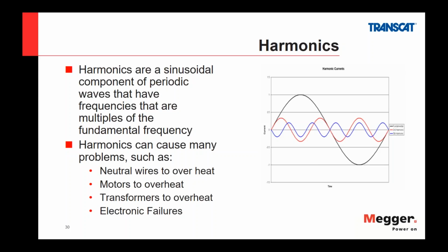Harmonics cause a lot of problems with overheating on motors and transformers, and even electronic failures. The overheating can cause premature failures to your equipment.